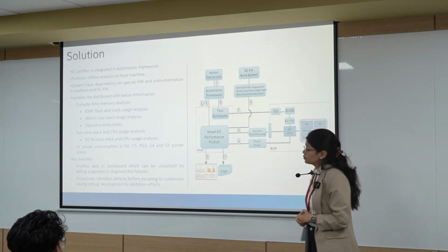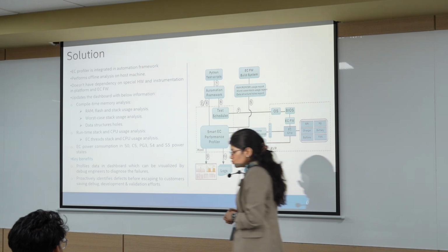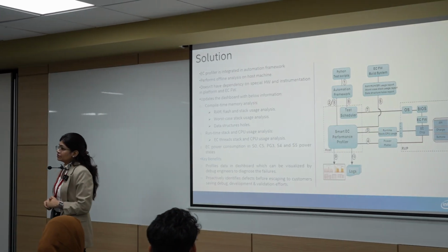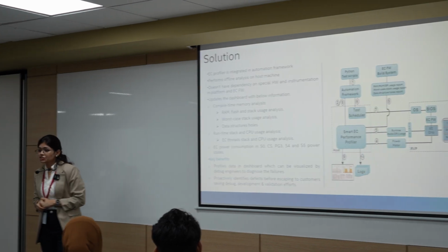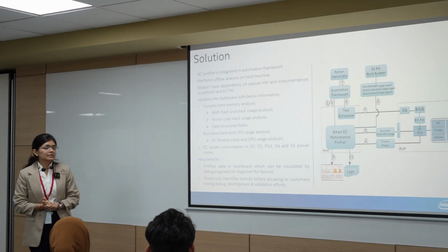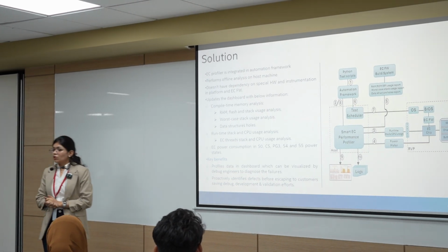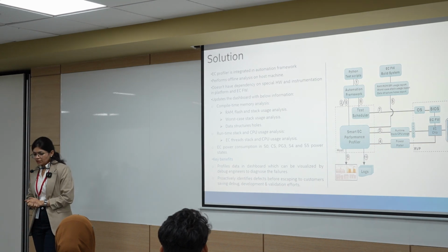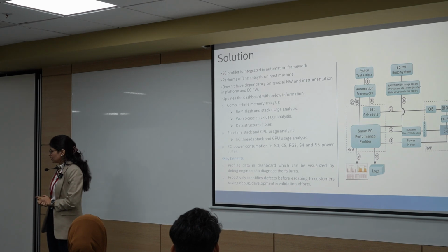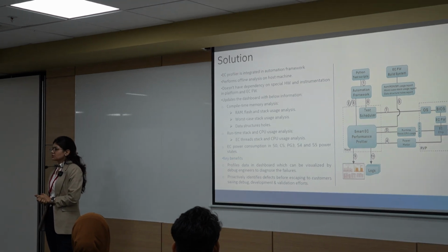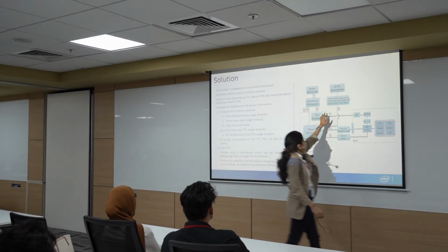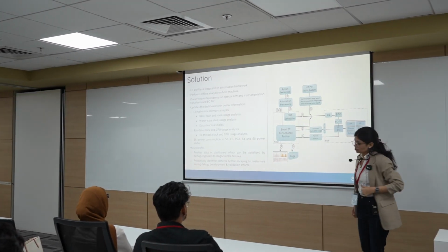Okay, before going to the solution, I want to tell you more about the Zephyr tools which we are using here. There are some prerequisites you need to take care of to get the stack details or the data structure hole details. There are tools supported by Zephyr, which are third-party tools actually. They are called puncover and pahole. It's mentioned here in this section, worst-case stack usage data and data structure hole.